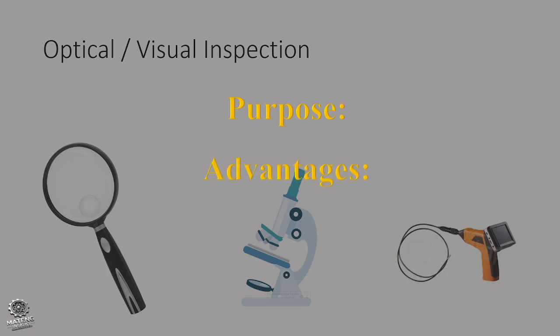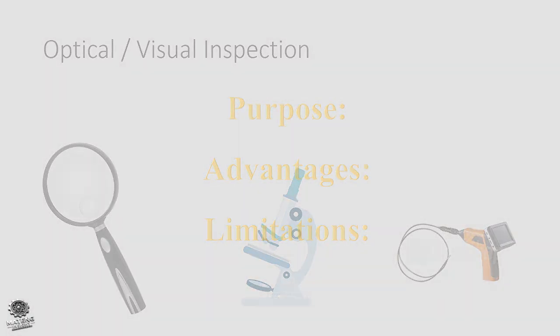The advantage of this method is low cost, fast, and simple to apply, non-contact inspection, and well suited for initial screening and monitoring. But limitations: this method is limited to surface and near surface defects and cannot detect deep or hidden flaws.